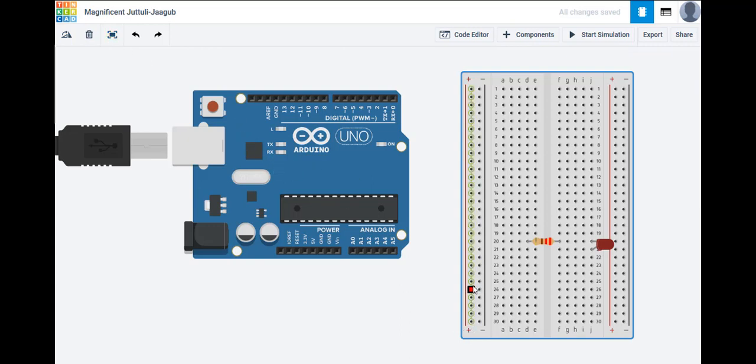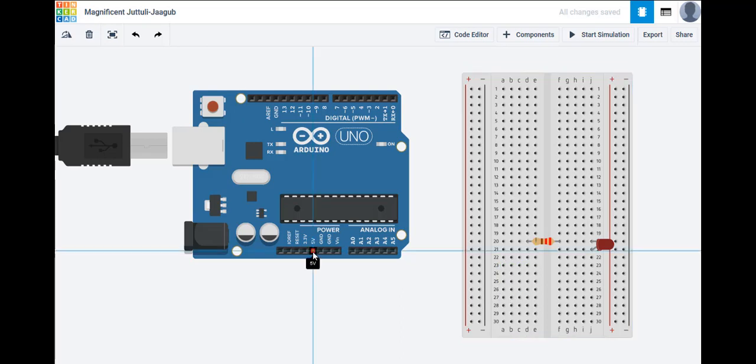Now, these power rails, positive and negative, are used to share out a supply such as this 5 volts between multiple components in a more complicated circuit than the one we've got here. So if I take the 5 volts, click there, drag a wire down to here, the blue lines will appear above and below to help you keep it vertical or horizontal, which keeps the circuit easy to follow when in a more complex circuit.